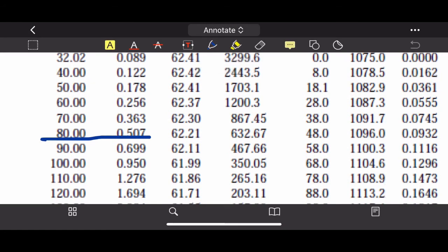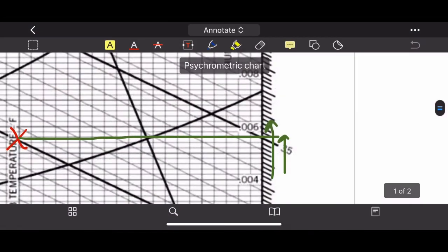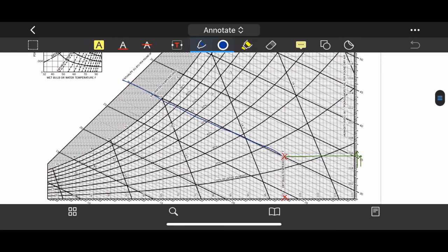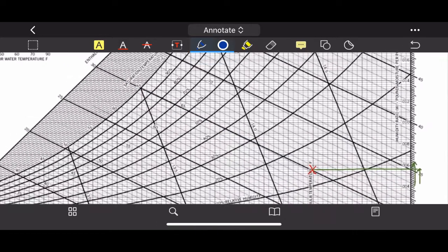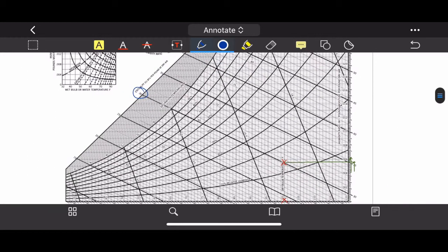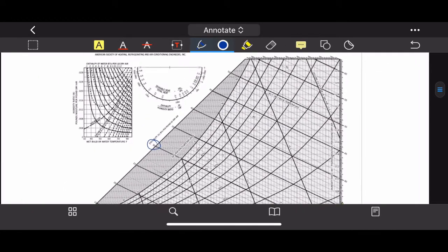Now next we need to find the enthalpy. Enthalpy is this line, right? Now I myself wouldn't mind to get the enthalpy at 30 BTU per pound of dry air, but if you take a look at the answer on your script, it is 29.8 by the nearest scale, but I don't mind. Myself, I would take 30 BTU per pound of dry air. The dew point temperature is given by, let's see, that's wet bulb.